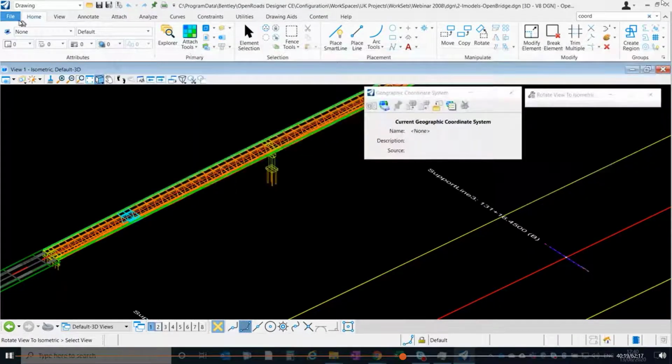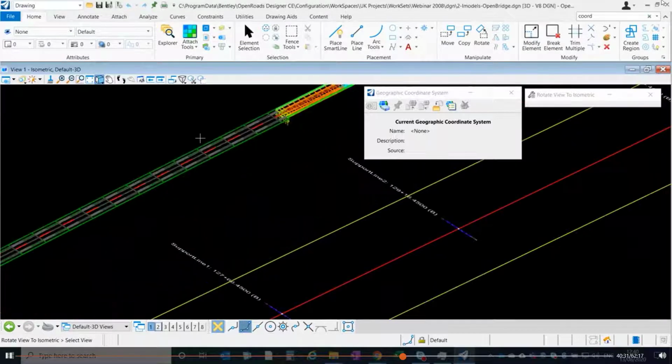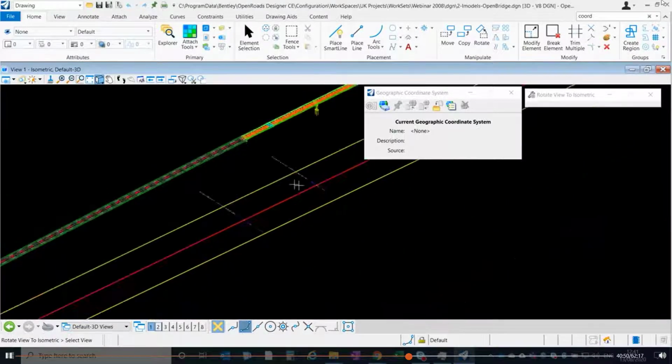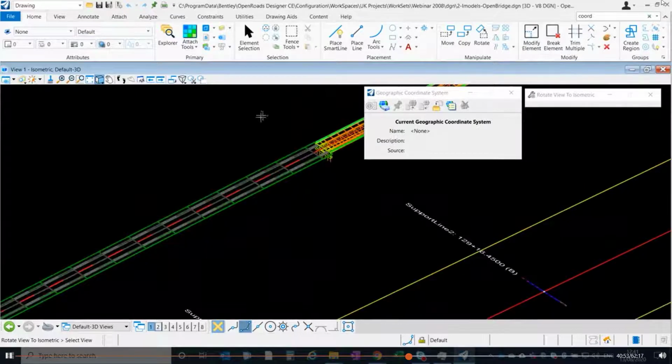The second option is to create iModels. If you don't know what an iModel is, it's basically a self-contained model containing all the different information of your project with the different schemas and everything. So every time you reference them, you don't need to worry about the references. You just have everything inside, and it contains all the information you need to know about your projects. So basically you can have the physical and functional representation of your projects inside the file.